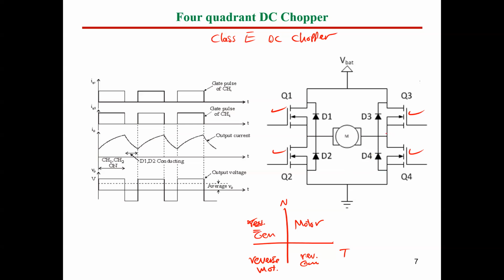for small power applications. So if you have a motor, for instance, like around a 40-watt motor, with a small voltage, like up to 24 volt, or 12 volt, depending on the motor you have, you can get a very cheap circuit composed of MOSFETs in order to control this motor.